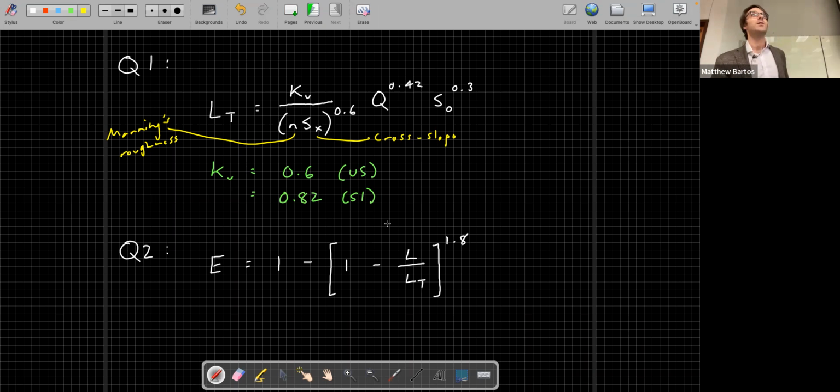So for curb inlets, instead of having simple and composite, they will be called either just normal curb inlets, or depressed inlets. There'll be another equation for depressed inlets, which is essentially the analogous situation to having a composite gutter. Those equations will be in the notes. I don't know if I'll have time to cover it, but it's very similar. Any other questions on on-grade curb inlets?